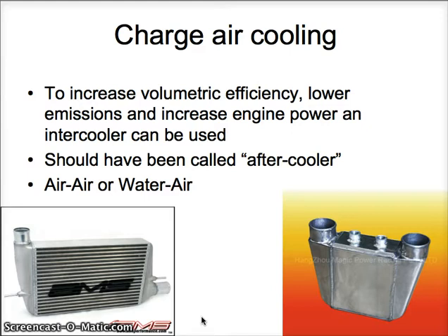Using strict terminology, it should be called an aftercooler, but everybody in the industry says intercooler. It could either be of air-to-air type, where the intake air goes inside and ambient air is cooling the charged air. Or in this case, you have the intake air going through this, and then you have water flowing and cooling the intake air.